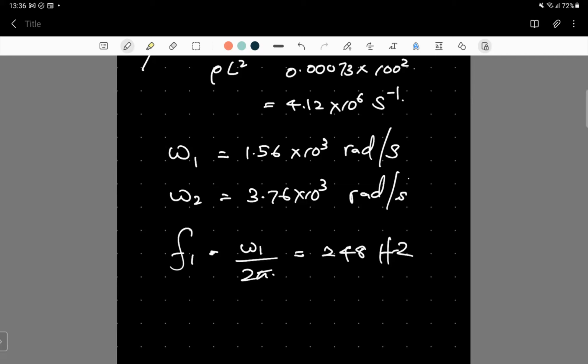It is the same procedure when you apply it also to a beam. It's just the fundamental equations change based on the type of element, but the procedure is the same, because when we move from a bar to a beam, there are additional degrees of freedom, and the stiffness matrix will vary based on the number of elements you use.